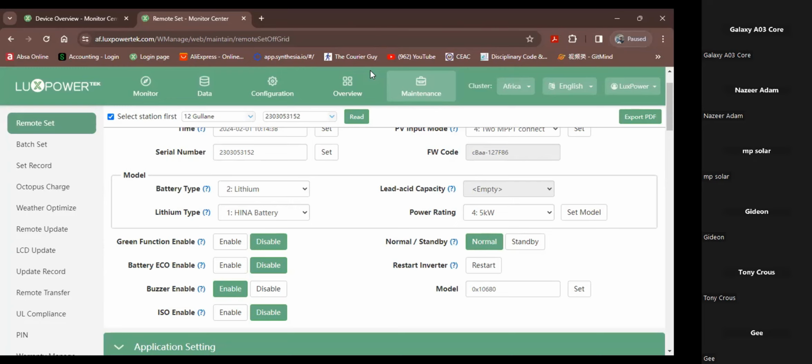Do you see the problem here? You're sitting with a 5 kilowatt inverter and a battery that can only really run at 1.8 kilowatts. And typically what will happen is if you have a spike load, it will set the battery into alarm, right? And it'll cut the EPS of the inverter, and you will have calls from your client. So it's always advisable to give your clients advice about their battery selection.